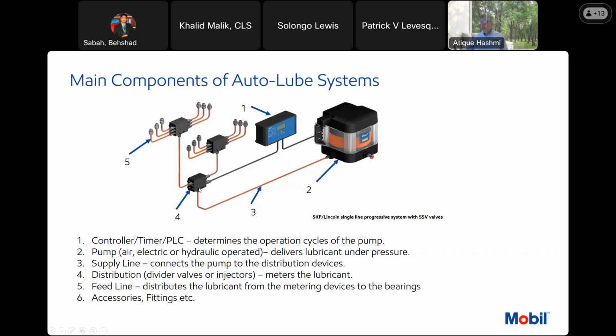So this one is a primary valve or the master divider block or valve. So usually when these lubrication systems are installed, there is a pin called cycle indicator pin, CIP, and I think I have that in one of the slides. So cycle indicator pin, and I'll talk about the disadvantage of this type of system, like a progressive system.